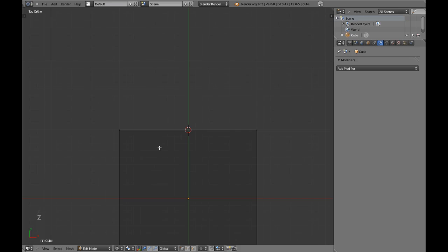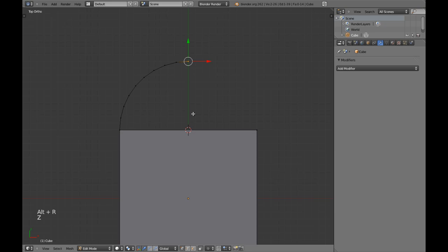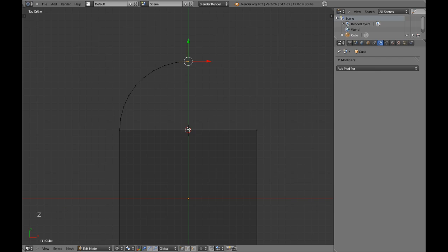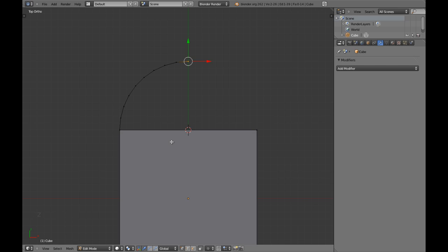The cursor is really important, because I will create spin with the cursor here, and you can see the result. Okay, but if I move the cursor right here and I use a spin, you will notice that you have a really big change. It is because spin has, as I told you, two references: the cursor and the view. Okay, so it's really important.